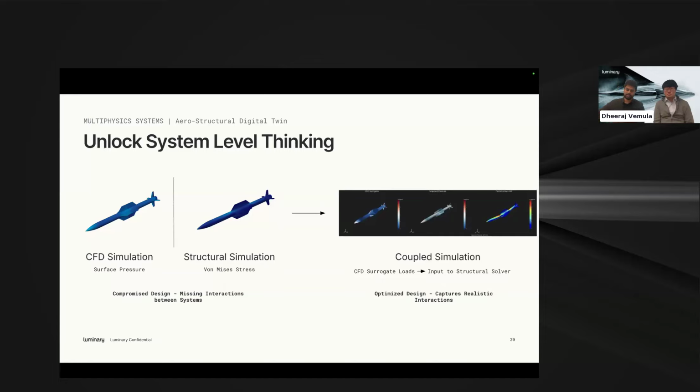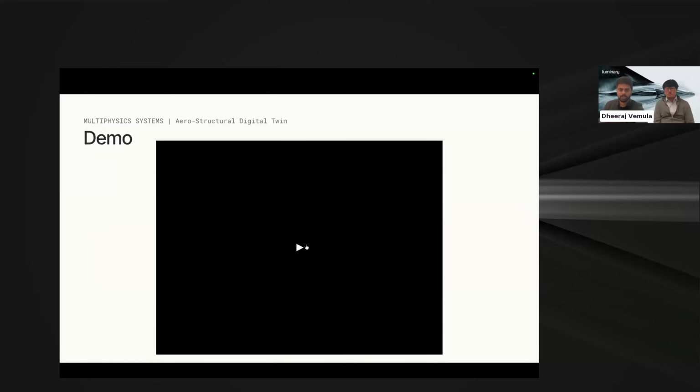We can even go a further step from there where you have maybe a structural surrogate model, and now you can maybe, instead of doing a complex, computationally heavy FSI, do surrogate-surrogate interaction based FSI early in the design process, but then the final validation can be your full FSI, which removes the requirement for compute-heavy FSI early in the process. So those are different things you can do. And what I'm going to show now is the one-way coupling of fluids to structures using the surrogate model.